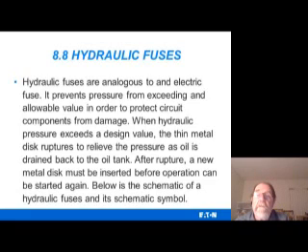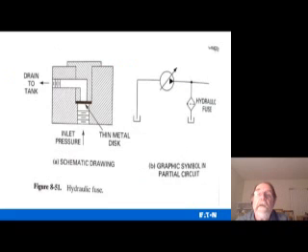Below is a schematic of the hydraulic fuse and a schematic symbol. And see here, there's your little thin disc, okay? And once it gets up too high, it pops this and it drains the fluid back to the tank. And that's what this symbol is here. And that's it.